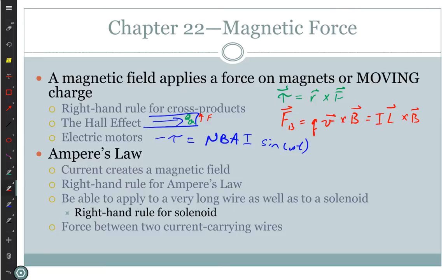But I've been saying all along that the protons are the positive charge and they're fixed. And so what we say in physics and engineering is that it was hole migration. And what's a hole? It's an absence of negative charge. It's a place where you should have a negative and you don't. And it's these places that are missing electrons that are migrating. So electrons are hopping, and it's the missing electron that is moving. Which is kind of convoluted, right? But we do have a positive charge carrier in that case.